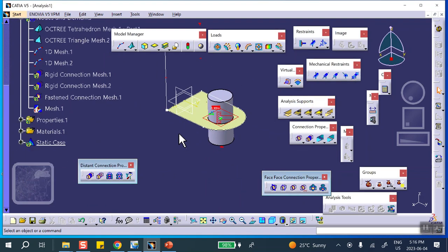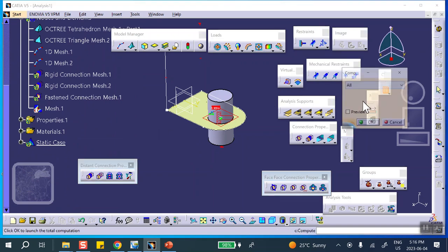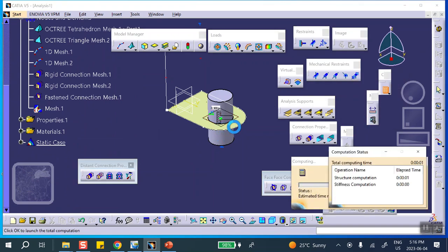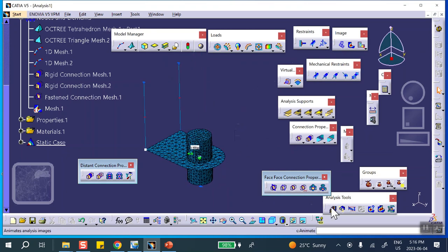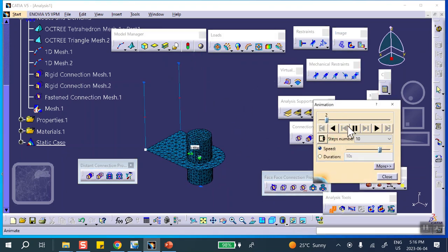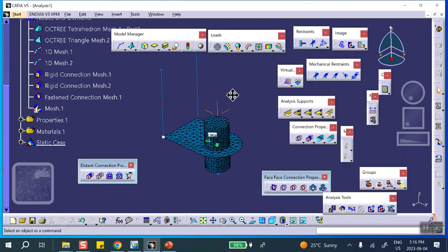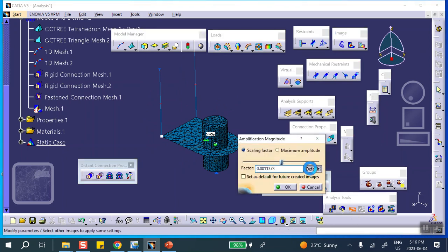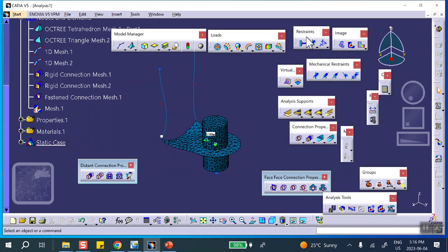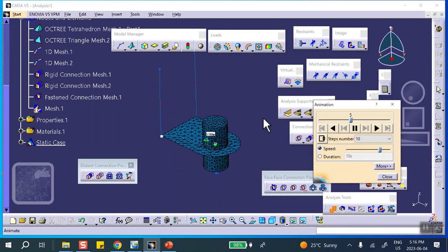And we're going to run it. This time it's going to work, and we're going to see how things went. Good. Look at the deformation. There we are. Animated. Now, if it's not showing anything, that's because, remember, we already asked it to show us something that went to infinity. So make sure you go to the scale and use default right there. Okay. So there it is. That's the way it should be, right? That's the way it should be.